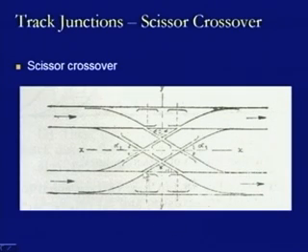Then there is a crossing at this location as well as this location. So, we have a wing rail in this direction and this direction, similarly this is a wing rail here and this is a wing rail here. This wing rail is extended so as to form a part of a diamond crossing, so this is coming here, goes this way, and it becomes a wing rail again on the other side, that is for this acute angle crossing. So, this is the way we are using the same rail section so as to become a wing rail or a lead rail at the same point of time.